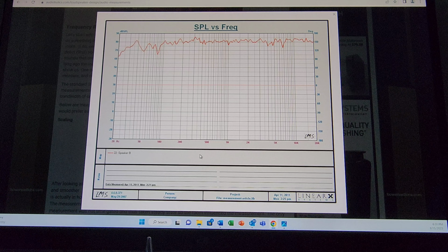And if you recall the earlier graph I put up where we ran the sweep in the room and we mic'd it, at about 45 hertz I was saying there was a noticeable drop off in bass energy. And certainly it looks like that's predicted here on that chart as well. In fact, the program says somewhere at about 50 hertz, so if we move across at 50 hertz, we probably end up somewhere over here.